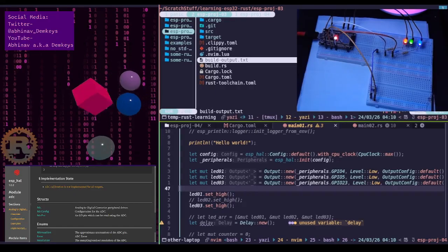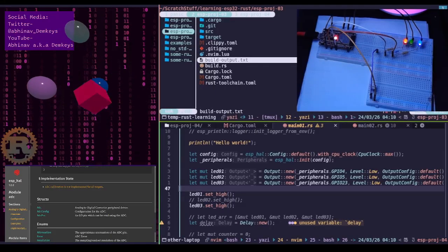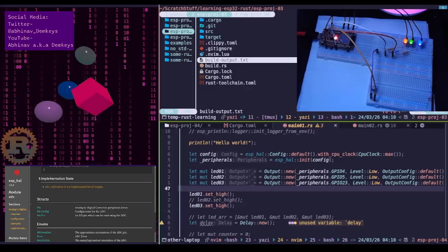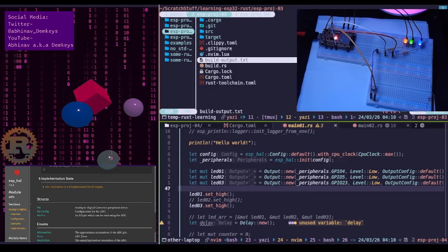Okay, hold on, I'm going to continue reading this. Voltage equals raw reading minus B divided by M. Now, every time you take a raw reading from the ADC, you just reverse the math to find the actual voltage.